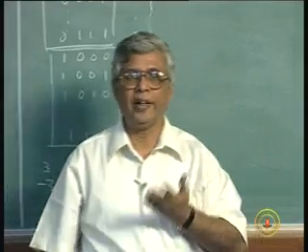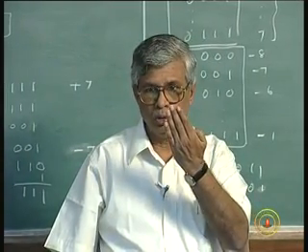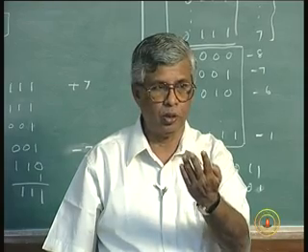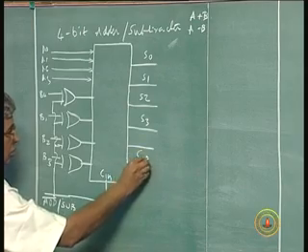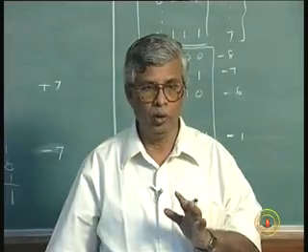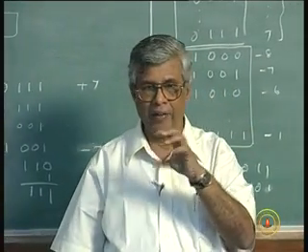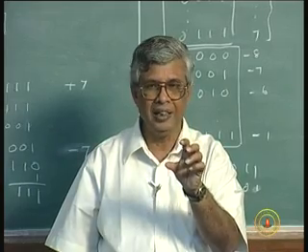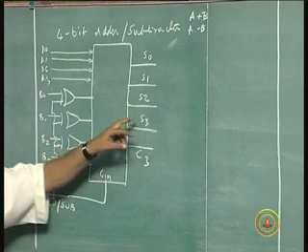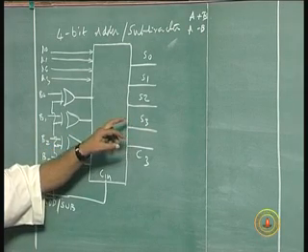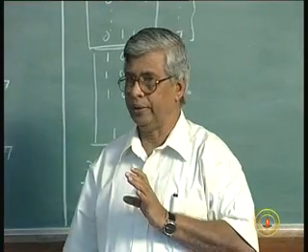Is carry significant or not now? Because the 4-bit adder will give you 4 sum bits S0, S1, S2, S3 and a carry bit which we will call C3. But does C3 have any use? No, because we are only talking of 3 bits now. The 4th bit is a sign bit, and the result will always be a 3-bit magnitude and a sign bit. S3 will be the sign bit, and S2, S1, S0 would be the magnitude bits.